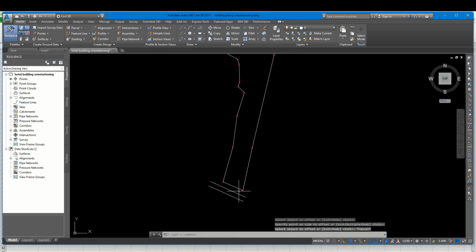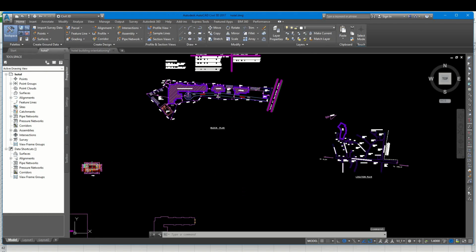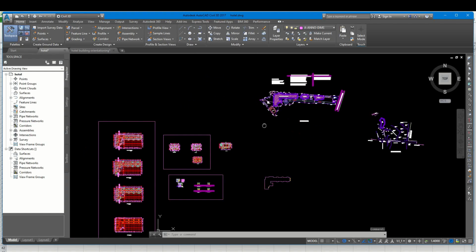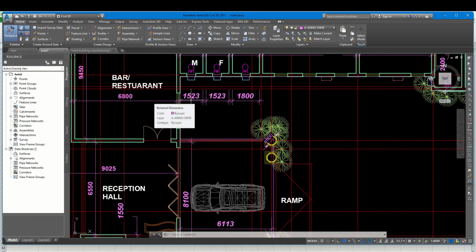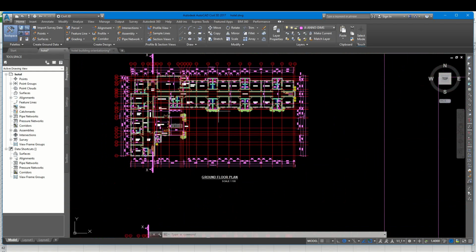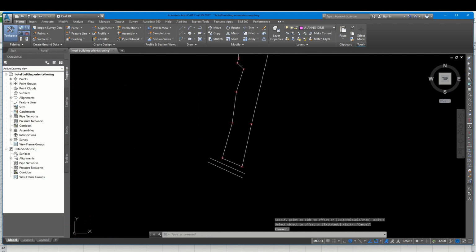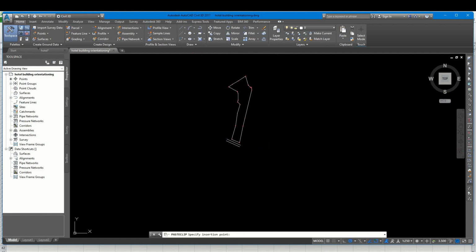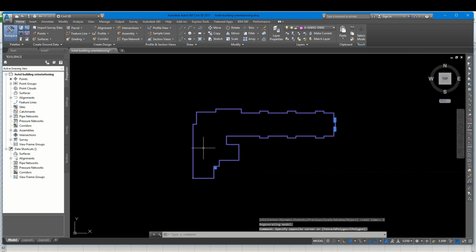It shows that this. And one thing you must put in mind, go to your architect drawing, you must follow and check well properly the measurement he is using, and he's using a millimeter based measurement system. So this unit must be converted when you want to import your block. So if I should copy this block from here and bring it into the original site that I want to orientate, so let's paste it. You see massively the block will never match because the surveyor point always come in meter and this came in millimeter.